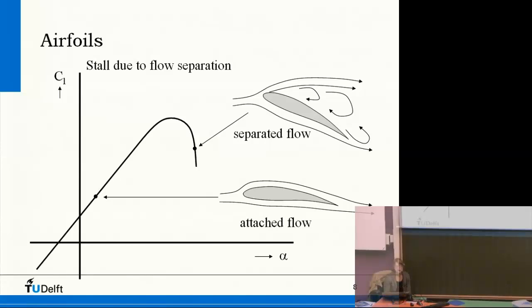The Navier-Stokes equations, which describe the flow, are a set of partial differential equations, a system of equations. They do have all the scales in them, but we cannot solve them analytically. So what we do, we approximate the flow solution on a certain mesh. And we do that, and the mesh looks like this. So in 2D, for example, you can have structured meshes or non-structured meshes.